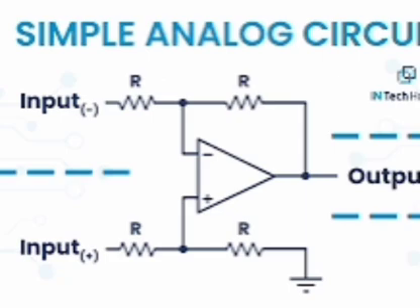Cascode amplifier is a cascade of CE and CB amplifiers, or a cascade of common source and common gate amplifiers. It can provide both voltage and current amplification, therefore it is preferred over the common base amplifier in radio frequency amplification and wide band amplification. Amplifier using FET and MOSFET.